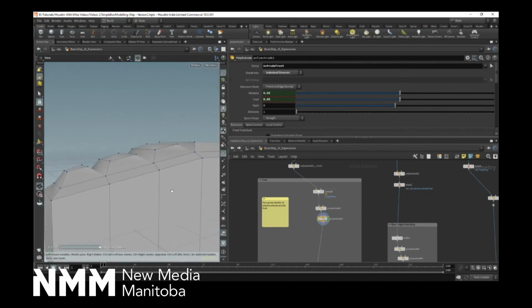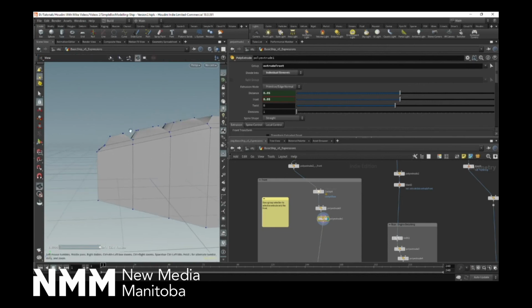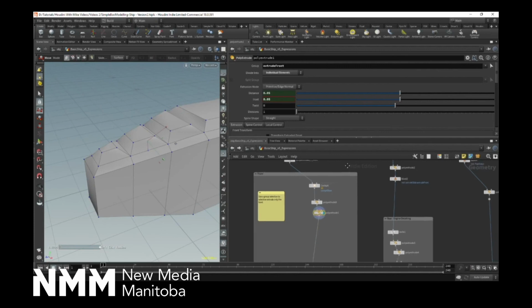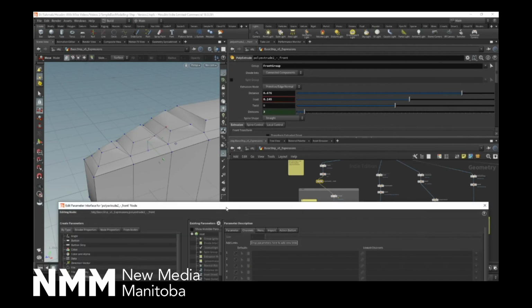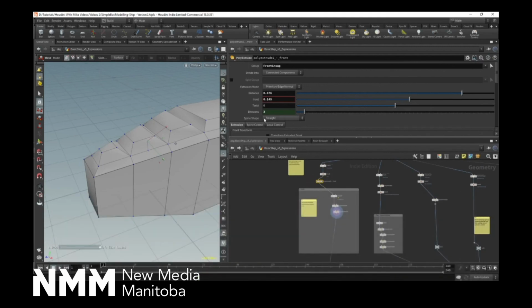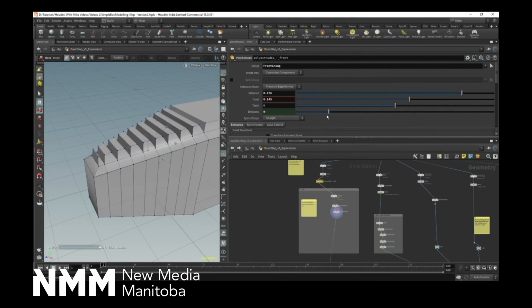One of the things I think is really cool here is you don't have to make a node for this or anything. A lot of these details are already built into your model. You can just start exposing them. So what I do here is I take my divisions, which is just a setting of poly extrude, and I pretend it's a control, and I add it to a node and call it, number of windshields or something. Now I could give that to a designer and they could go crazy, adding as many of these as they want. And it's really easy to see these variations.